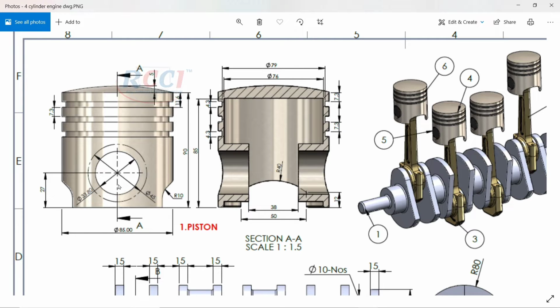Now let's make this hole 27, distance from bottom 33.8 millimeter. This is a through hole. Then there is an extruded body inside, and that is 45 outer diameter. You will see it from inside, and for the 38 millimeter distance, if we choose center distance, we will make a 19 millimeter offset. There is one more cutout. See here, R40, 12 millimeter, 50, these are the cutout dimensions. So I'll show you how.